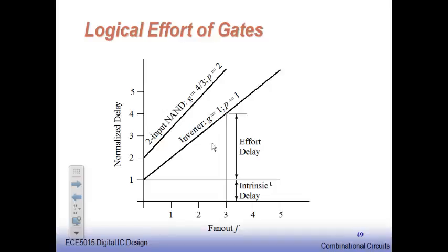And one of the assignments is going to be this way. So I have given here intrinsic delay and effort delay. Why do I call this effort delay? Its own intrinsic delay is its own capacitance getting charged, and because of that whatever be the delay incurred. Whereas the other output loads, what I go for connecting in terms of the other combinational gates, and I calculate the logical effort for such gates, and I go for counting how many fan outs I am going to be having. So G times F, I go for doing it.